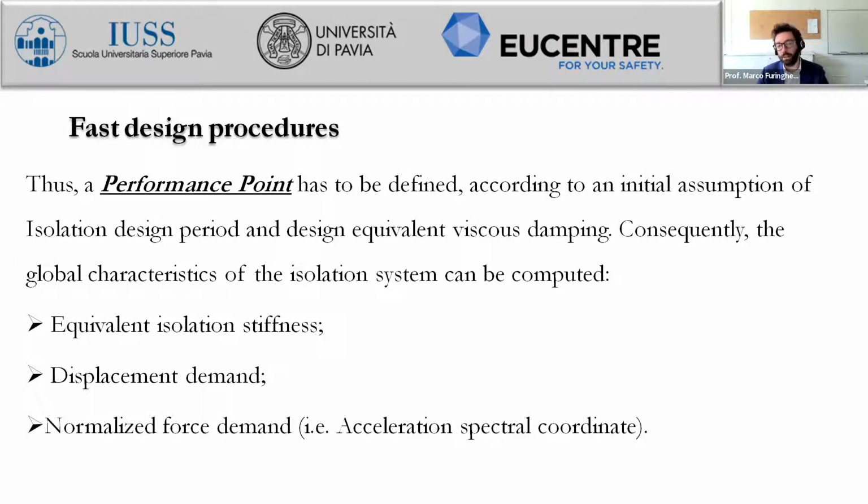The main initial assumption is related to the performance point of the overall structural system, which is directly related to two very important components. The first one is the design period of the overall system, and the second one is the equivalent viscous damping, which rules the energy dissipation capacity of the overall isolation system.